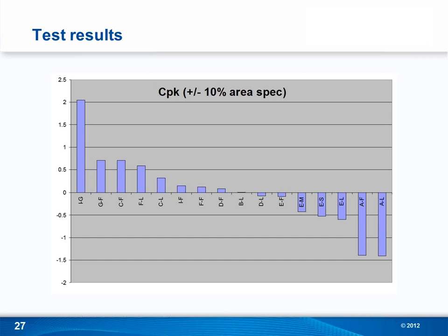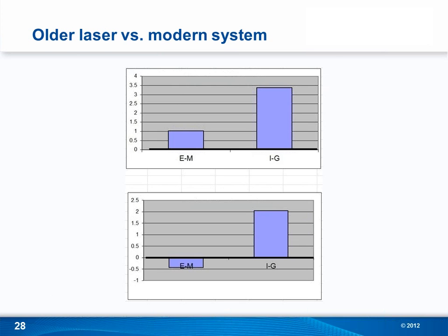So what could cause that particular kind of a problem? Well, the number one is poor data prep. Using instructions wrong, using the wrong beam diameter in the system, in the calculation of the cutting path. So the stability of the beam is important, and you have to take into account what the size of the beam is. The laser system is like a milling machine, and if you don't know the size of the bit in your milling machine, you don't know what size openings you're going to get.